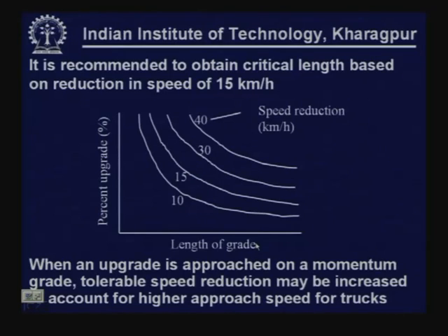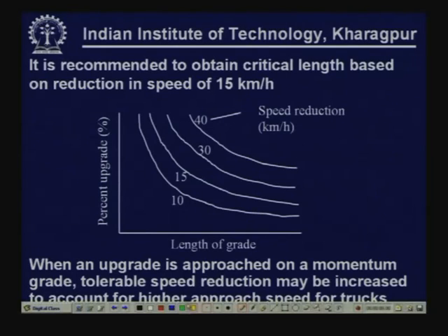For a particular percentage upgrade, if we consider the allowable speed reduction as 15 km/h, then there is a corresponding length requirement.